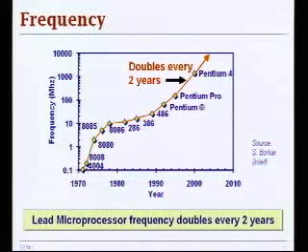So, important: number of transistors doubles every 2 years, frequency doubles every 2 years, and die size increases by 14% every 2 years. What enabled Moore's law is improvements in manufacturing technology that reduced defect density, which we will talk a bit about today, and therefore the cost of a die didn't increase much. And we also have to attribute this advancement to shrinking of transistor dimensions, and also design cleverness and new circuit ideas.